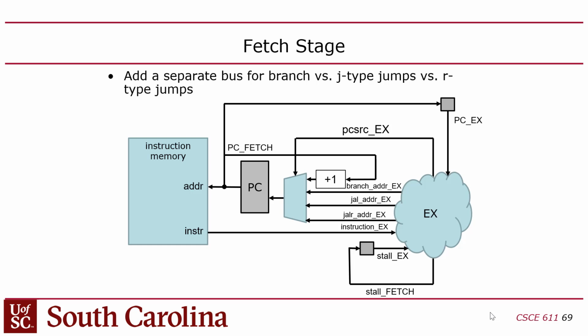You guys with me? So in other words, it's like a note to self. The control unit is sequential. I'm sorry. No, it's not. It's combinational. The control unit is combinational. It has no state, has no memory. So it's going to use this register as a way to make itself remember that in the previous cycle, it wanted to stall the next instruction.